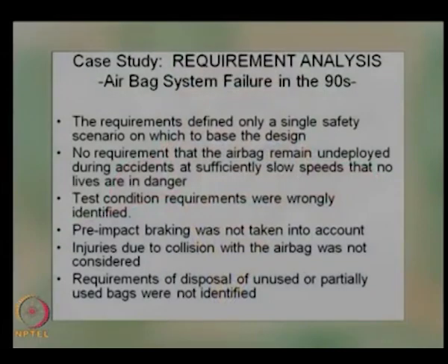Then again, pre-impact braking was not taken into account. Normally before the accident the brakes will be applied by the driver, and that reduces the speed of the vehicle, and because of this speed reduction the driver will always be moving forward and hitting the steering assembly, and that was not envisaged in the test condition. It was always assumed that the airbag should deploy only after there is a collision.